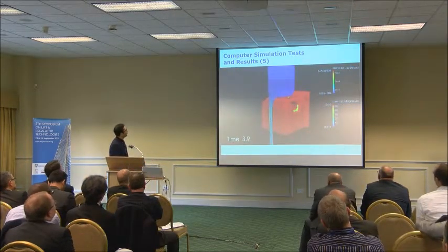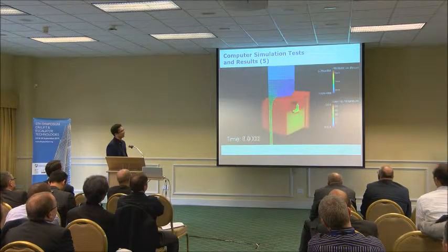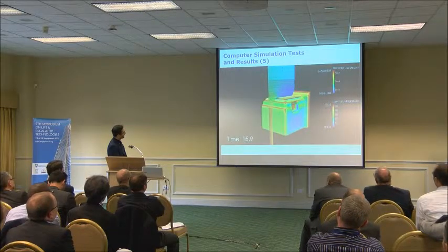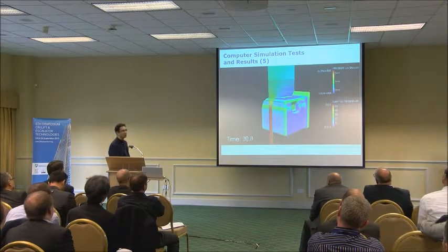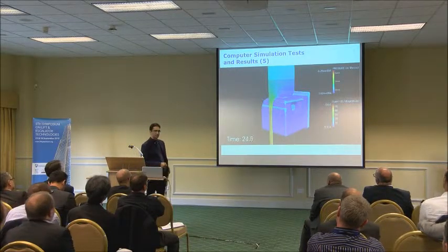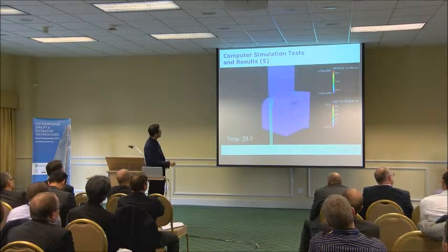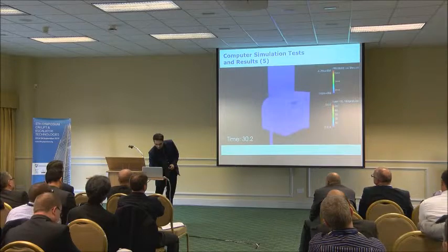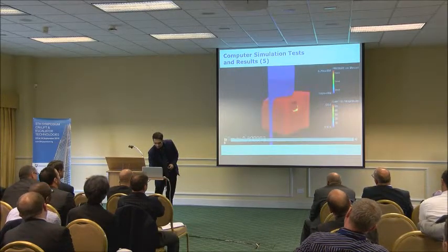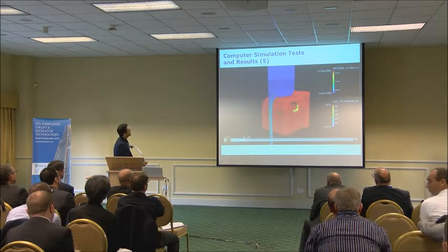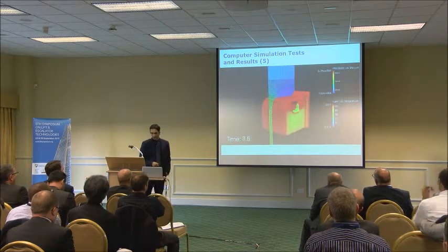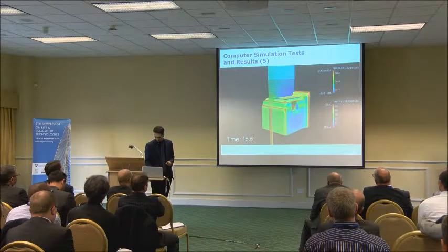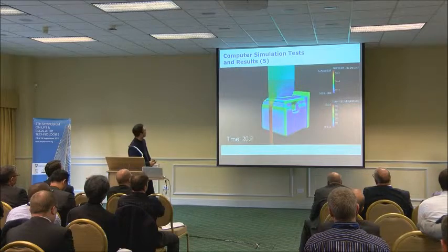We also added the deformation of the top shroud into our simulations. While the constant travel speed will be 10 meters per second, on the side of the elevator we have up to about 54.4 meters per second, which has increased massively. But we can also measure the pressure on the top shroud and its effect on the stress on the top shroud. So one more time. The pressure on the shroud itself can reach up to about 62 kilopascals. It reaches the maximum and constant, and then it settles down.